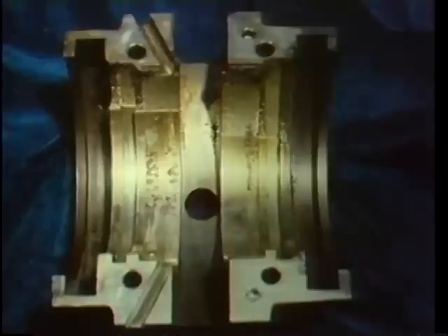Now, pressure's effect on viscosity is the opposite of temperature's effect. When pressure goes up, viscosity also goes up. This is a factor in high pressure systems where thin oils are used because they will thicken enough to work properly at operating pressures. Also, high loads can create high pressure in a lubricant. If the lubricant is too thick, the resulting increase in viscosity could prevent the lubricant from working properly. This could cause equipment failure.